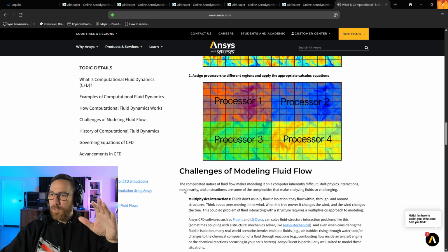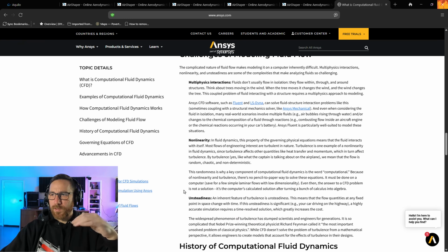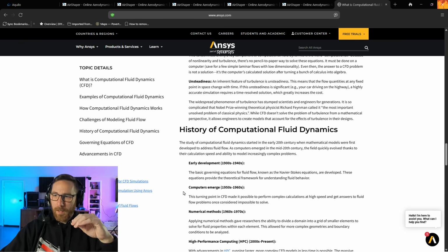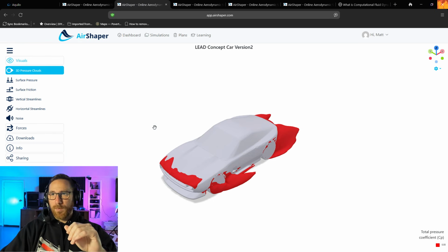Now, while most of these are going to solve locally, sometimes they'll be able to solve across multiple cores. It will be a system resource problem. And obviously Fusion has simulation as well, but Fusion doesn't have flow simulation. It does have thermal, but it doesn't have thermal flow. And so that is a big distinction that we should understand.